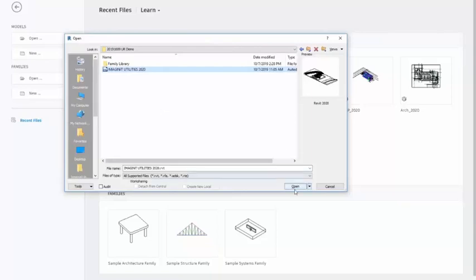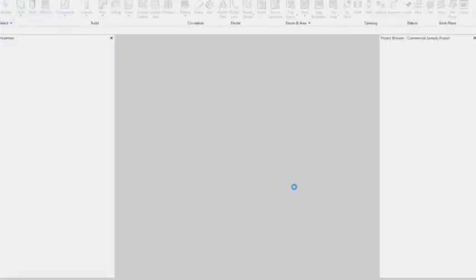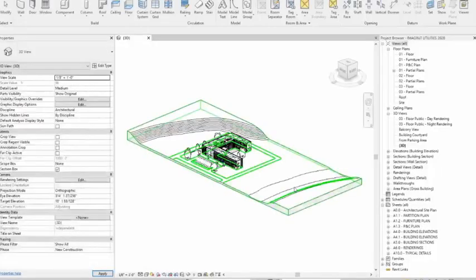Okay, and then we also have some questions around duplicating a sheet and views and how the IMAGINiT Utilities tool is different from the one that's built into Revit. Which one was that? Sorry. Duplicate a sheet. Yes, so it's the same 3 options: duplicate, duplicate with detailing, and duplicate as a dependent.